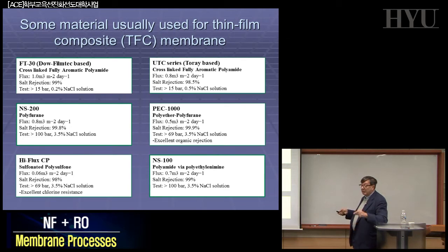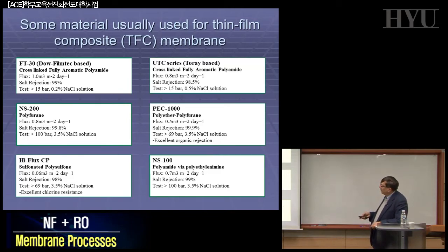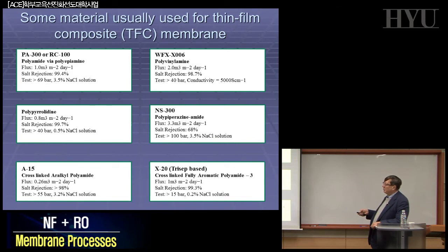So you will find, and these are asymmetric membranes, a dense skin on the surface, very dense, and porous material on the back, giving mechanical resistance and no high pressure drop in the porous part. And the results are quite interesting. One thing here just to mention, to remember, you will see some of these materials, for example, this one, polypiperazinamide, complicated materials, a little bit expensive, difficult.